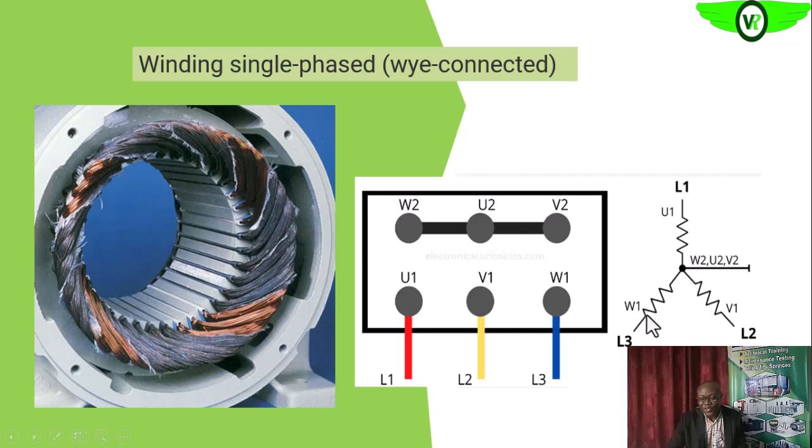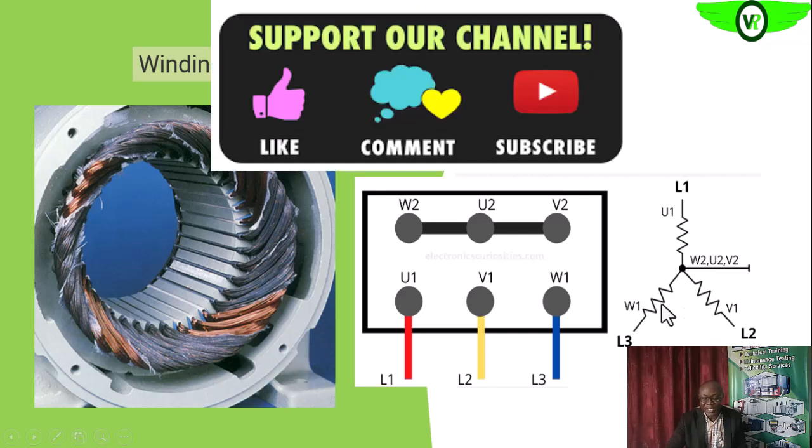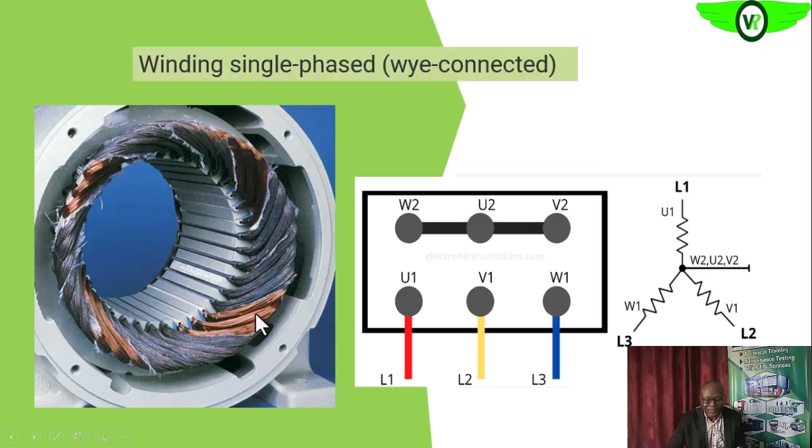Okay, so this W1 and V1 will now be subjected to excessive current. That is, more than normal current will now flow through each of these 2 windings. Are we getting it? So once excessive current flows through each of these windings, remember they are made of copper wire, which is a resistive material. Copper is resistive in nature. So as current is flowing through it, the I squared R effect will set in, thereby increasing the heat dissipated on these windings.